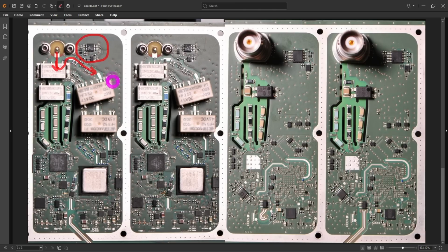And once you come into the 50 ohm path, you can see that there are several different possible paths that you can take over here. One of them even goes from the outside and comes back. This is the back side of the same thing, and that could be various attenuation settings and even filters in the front end for aliasing and so on. Ultimately, all of that ends up in this big IC, and this is the 2 gigahertz bandwidth IC, which conditions everything. This itself seems to have two different outputs. This looks like an LC filter over here, and perhaps that is part of, again, anti-aliasing filter in the front end.